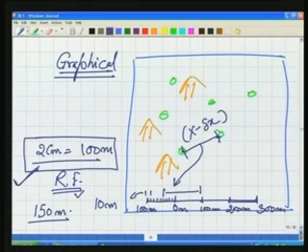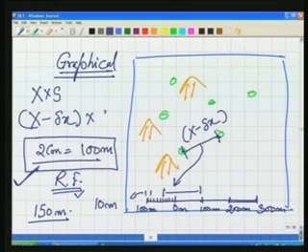So you will compute a distance which is wrong, because on the ground the distance is x multiplied by the scale, not x minus delta x multiplied by scale. But we will do it like this, because what we are measuring on the map is x minus delta x. We do not know what the x was unless we know the amount of the shrinkage.